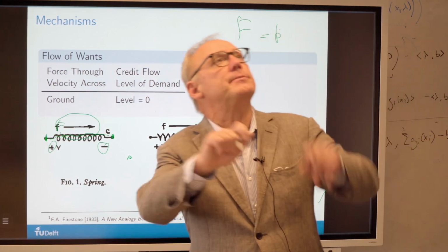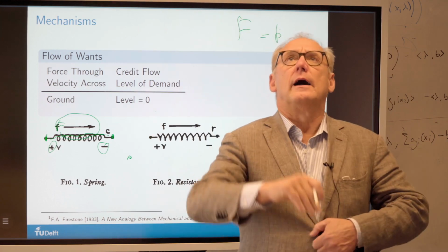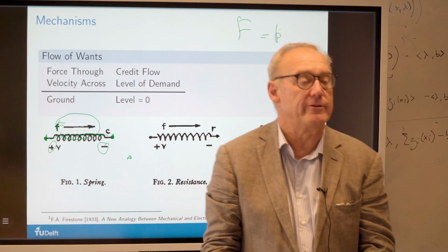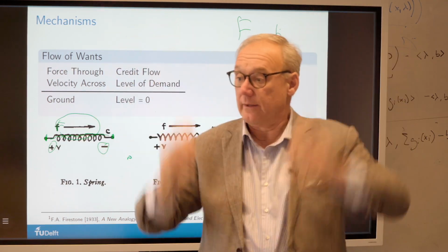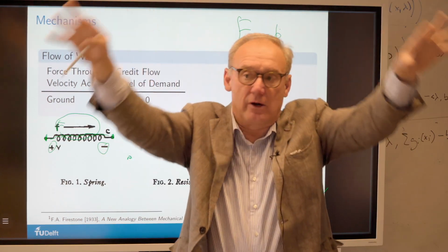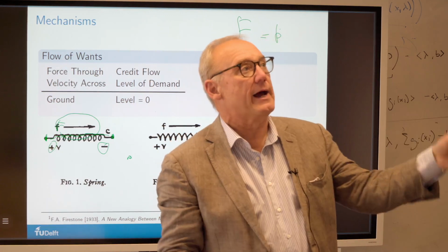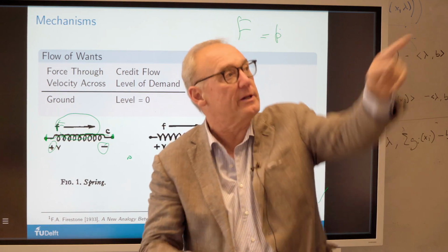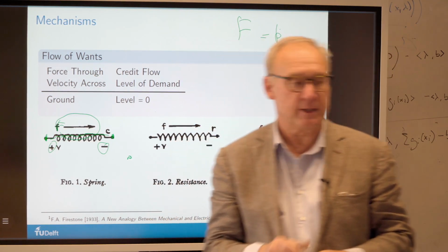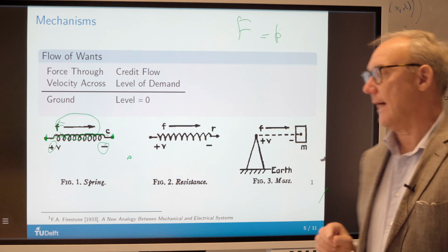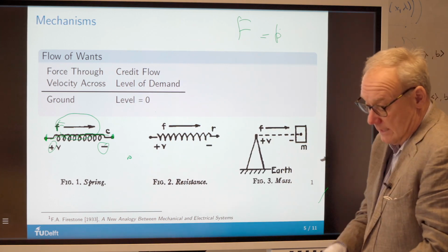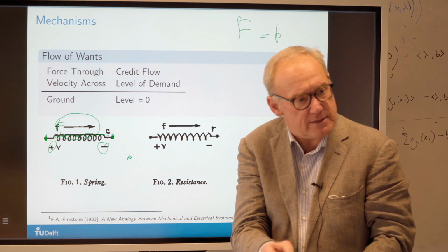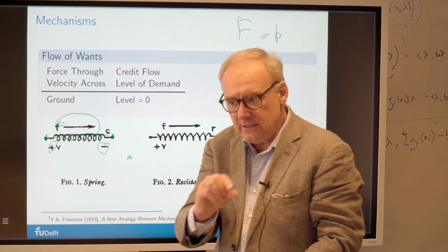If I look at this building, I'll see the roof. And you'll see it's just flowing through the beams into the ground. The momentum gets poured in by gravity. And it kind of flows like that to the ground in flow lines, and when it has to pass a corner, the flow lines are getting crunched up and the beam will break there. All right? Because the density of the force flow line is exactly what gives you the stress. So if you do statics, you get the stress tensor, and it will measure how dense these flow lines are.